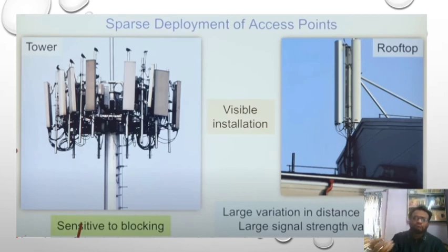It is noted that there is some noise to consider. For the bit error rate, Eb/N0 is there, so the transmitted power should be high, and again high power transmission leads to a rise in temperature and an increase of thermal noise. So it is not efficient even over a large distance, due to attenuation according to the Friis transmission equation. The signal strength is reduced. Moreover, this requires very high power and causes losses also.